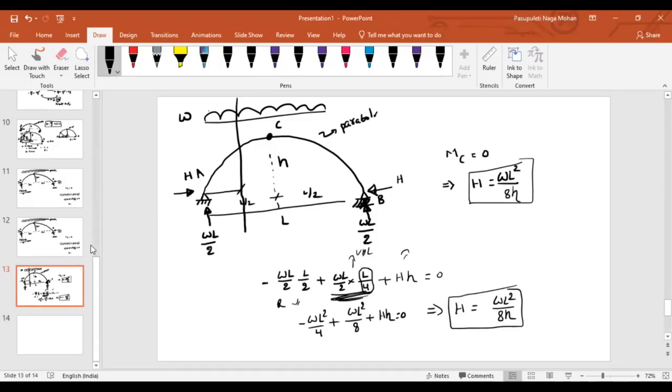at a distance of x from this support and find out the moment at that section. You know the rise. What is the y? If it is parabolic, I can represent it by using 4h by L square into x into L minus x. Now, write down this bending moment equation. Moment at any section xx. And simplify the equation and let me know how much you are getting.